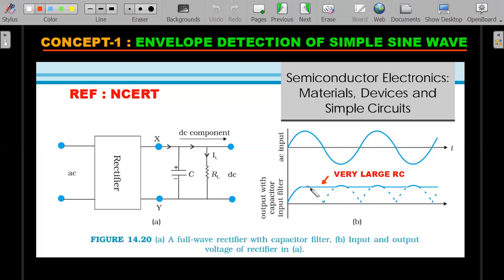So in general, when the decay starts, remember the input signal is also going to go through this entire cycle, and again it is going to rise from here and it meets this decaying curve at this place. And once the meeting point takes place, the diode here will become forward biased again, and therefore at this particular place the curve will follow the rule.